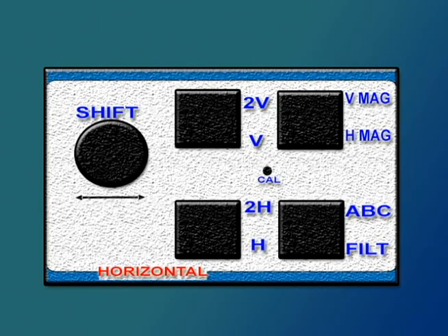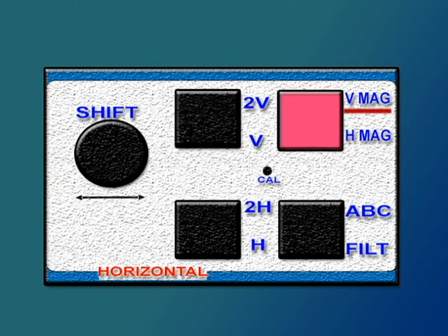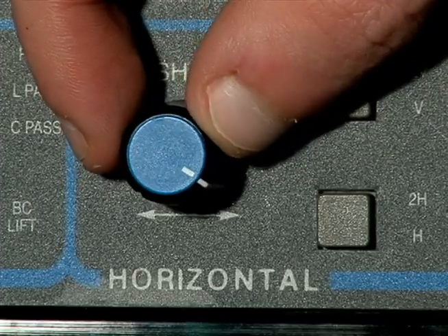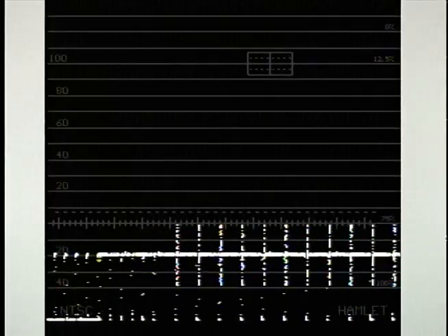Vertical blanking. Identify the vertical blanking interval. First select the color bar from a camera and then set the display control to 2V. Also set the mag control to VMag. Rotate the horizontal position control until you see no signals above 0 IRE. There should be 18 to 21 dashed scans. These lines represent the vertical blanking interval.